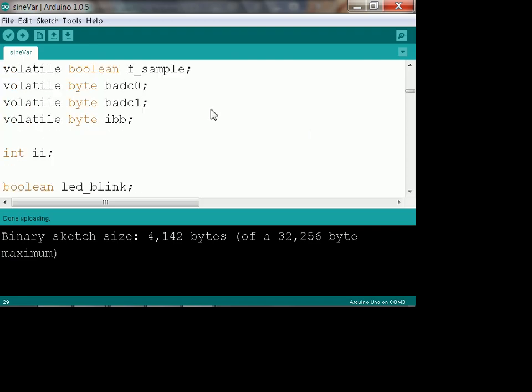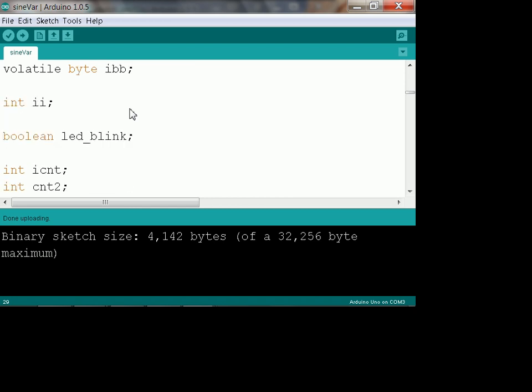Let's see now, what else do we have? This is an A to D converter, ADC0, and here's another one, ADC1. One of these ADCs is used to read in the variable resistor, and the other one is used to read in the audio. So two different ADCs are needed for the two different things. The variable resistor is completely programmable.